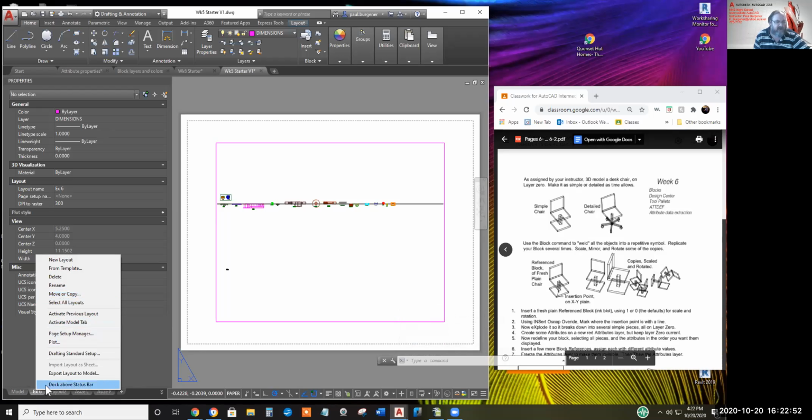Once you've put in a title block and border and your north arrow and maybe a bar scale, depending on the size of the sheet of paper, don't rebuild all that stuff. Copy it for the next project you got.